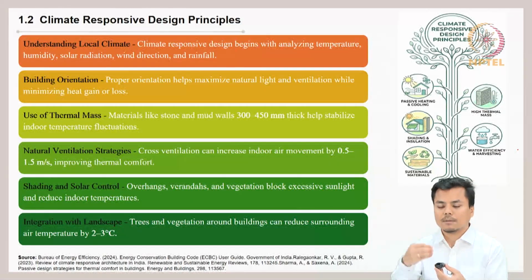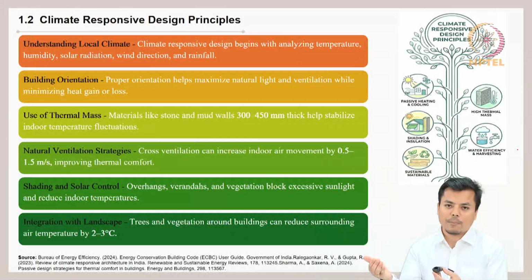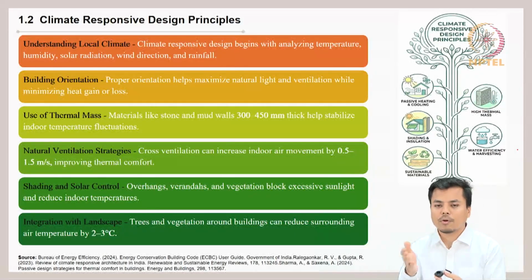It actually rises from the east and sets in the west, but there is a slight tilt of the sun that happens generally in the south direction for people who are residing in the northern hemisphere. So there is a tilt of the sun towards the southern direction during summer months, and in winter it is very slightly inclined somewhere between north and south. So that is there on the orientation side, and that is what has to be considered properly in the design, the orientation.